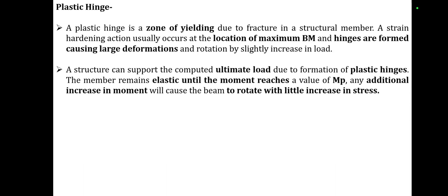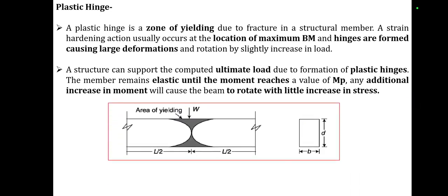Then a structure can support the computed ultimate load due to the deformation of the plastic hinges. The member remains elastic until the moment reaches a value of Mp. Any additional increase in the moment will cause the beam to rotate with little increase in the stresses.